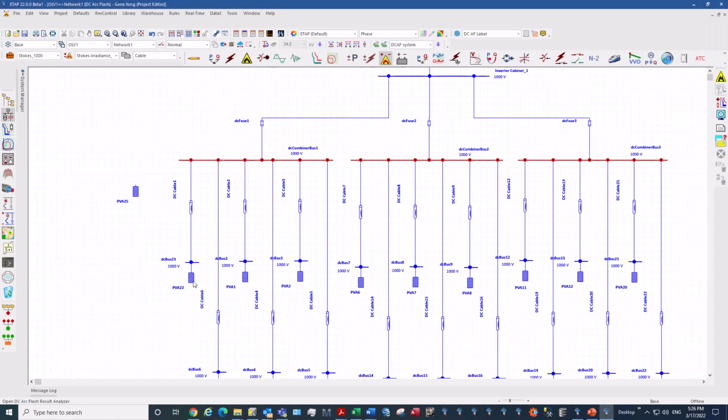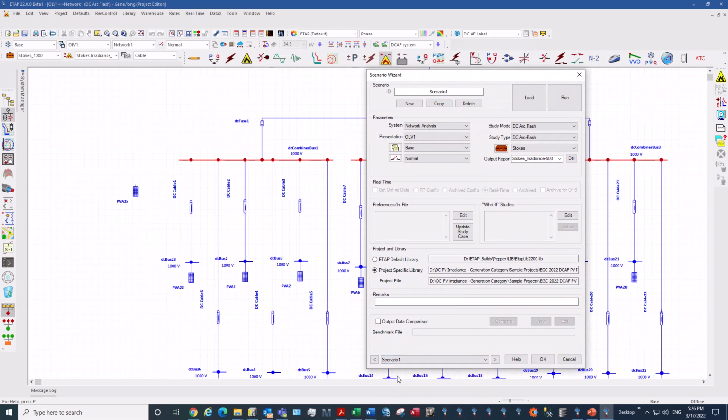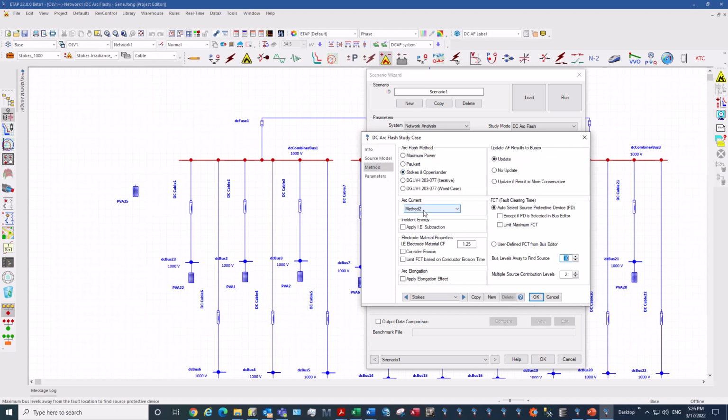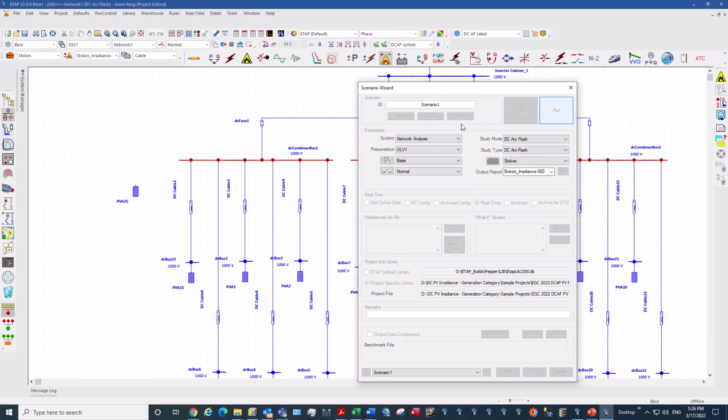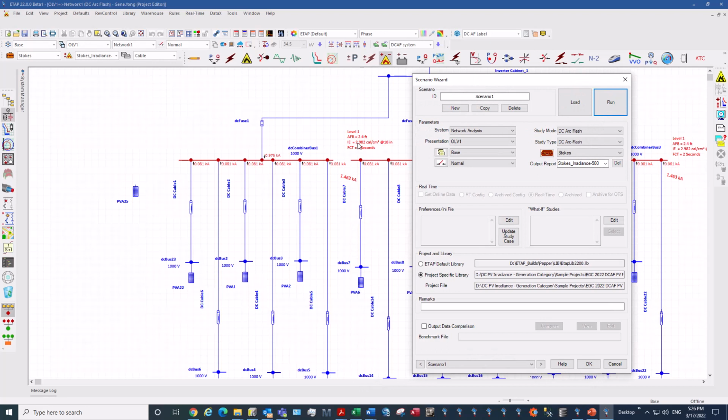Now that we have specified the PV array, the bus enclosure parameters, and the arc flash study case settings, let's run one study using the original settings I had set for the 500 irradiance. So in this case, remember how I selected in the source model at 500, and the Stokes and Oppenlander with using method 2 arcing current determination. You'll see that in this combiner box, I will get roughly 3 calories per centimeter squared for 2 seconds.